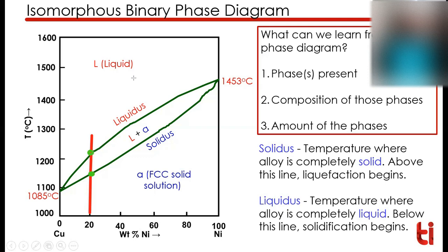The reverse way: the upper point is the start of solidification, when you are coming down and solidifying. This is the first cutoff point on the liquidus boundary where solidification will start. And the point where solidus intersects is where solidification will stop, meaning the material has completely changed into solid.